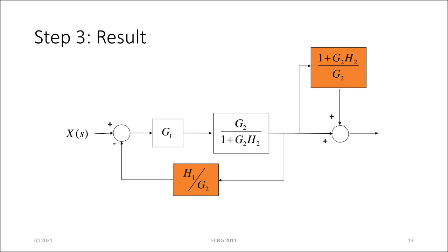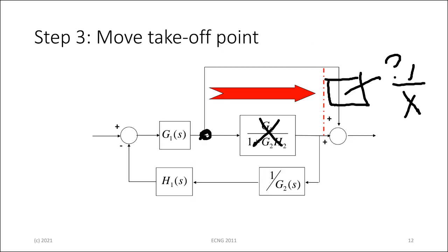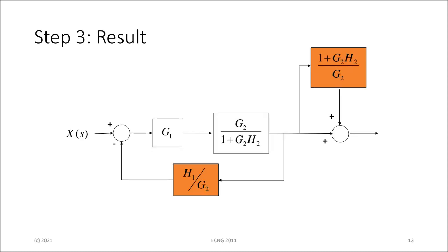So we're almost there. Let's back up a little bit. I've also combined these two. These are two cascaded blocks, so you could combine these two now into one. So I did two bits of simplification. Don't do too much on one diagram. It's always good to do one process per change on the diagram.